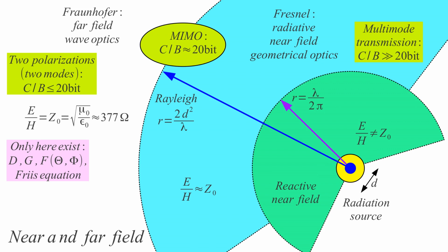140 years ago, 130 years ago, Heinrich Hertz tried to prove the far field phenomena here, but other people experimented at much lower frequencies, like the many early radio experiments, like Nikola Tesla, like Guglielmo Marconi, and they didn't know that, but they used a much lower frequency. That's the reason why the lambda here, the wavelength, was much higher. And all their first experiments took place in the reactive near field, where conditions are much different.